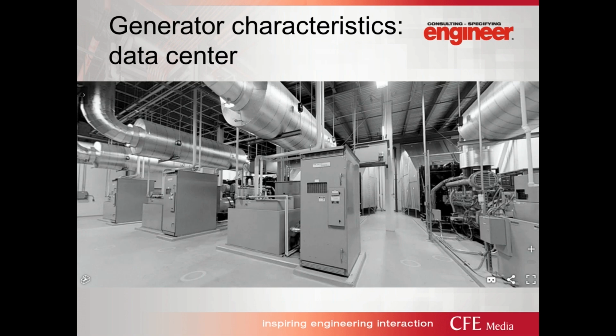So I think one key difference with data centers as opposed to hospitals is that for many of them, the load is almost all optional standby. We're not as encumbered in those facilities with meeting NEC 700, 701. We're not dealing with elevators sometimes, fire command centers, atriums, and things where codes are dictating what you need to do, and AHJs are upholding that.